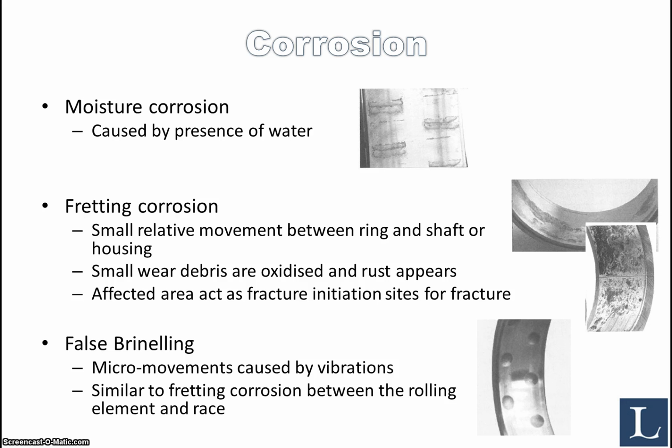What can be very negative for the bearing is that this affected area may act as fracture initiation sites, and you definitely want to prevent that. Then there's also something called false brinnelling, where you have a stationary bearing, and this bearing is subjected to vibrations, and this micro movement will cause a sort of fretting action between the rolling element and the raceway.